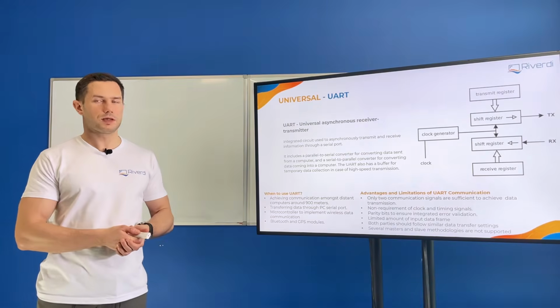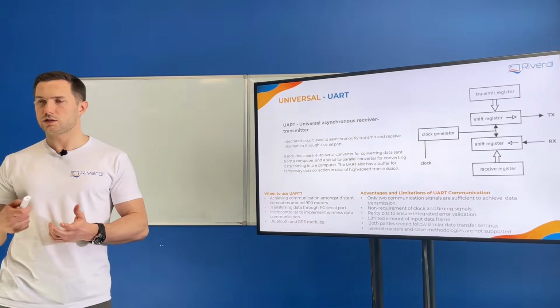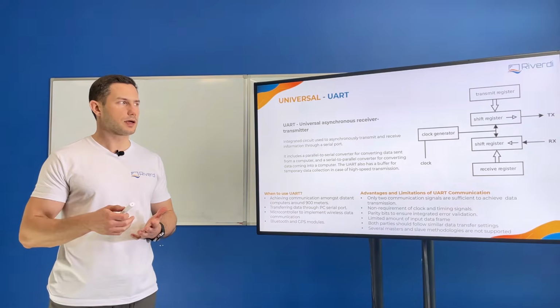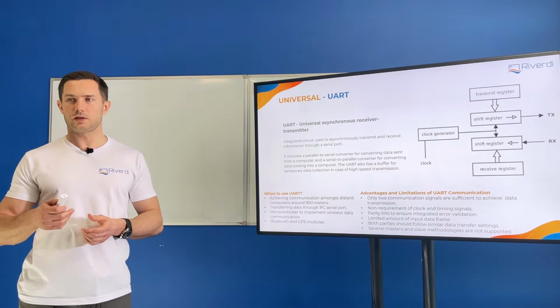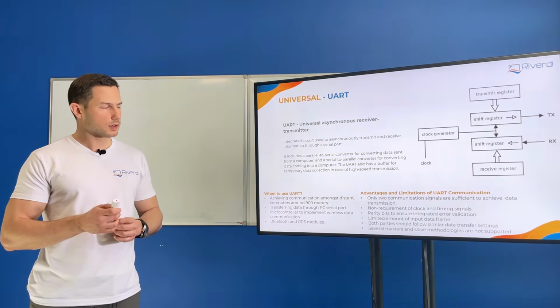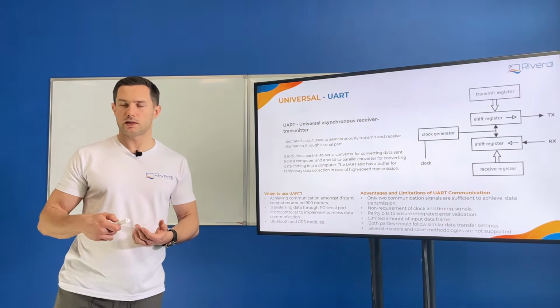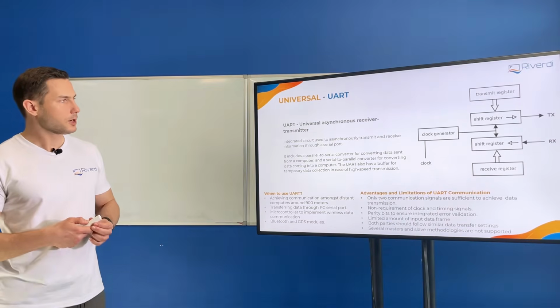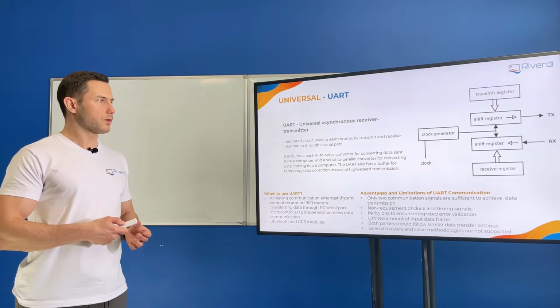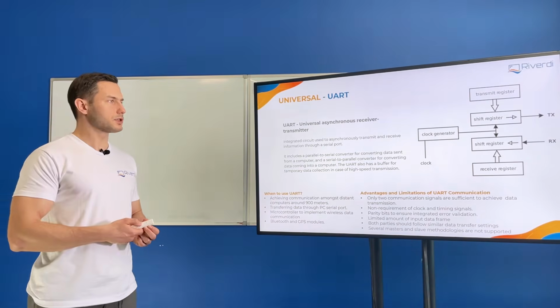You can use SPI interface to drive them, and still you can have high resolution, even as high as 1280 by 800 in a 10.1 inch display with the relatively simple microcontroller and a simple software to drive it. So as I said, if you want to use a slow universal interface, you need to use intelligent display.